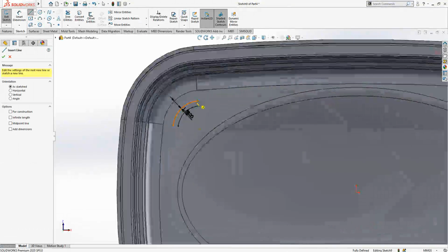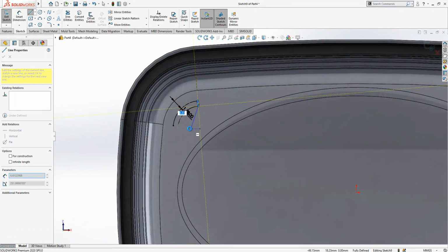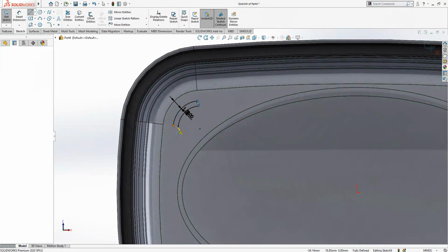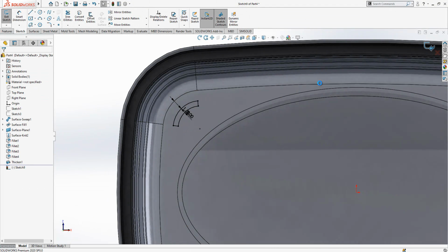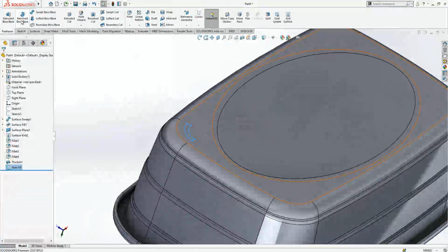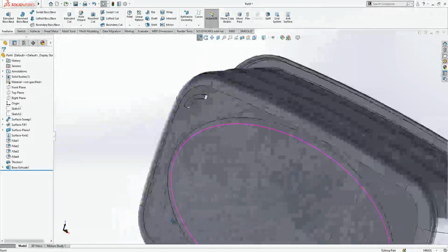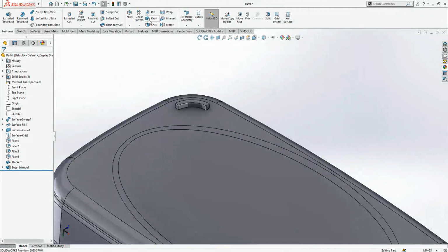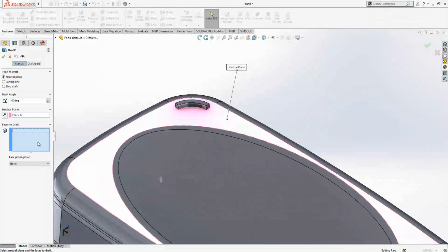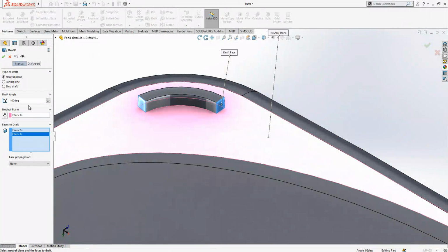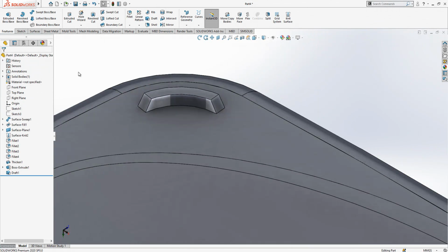And then I will combine these points with a line. And then I will make an extrude 1.5 height and with some degrees, 5 or 2. Let's make it 2. And then I will create a draft. Selected only these 2 surfaces, and I will make a 30-degree draft. I'm going a little bit fast, I realize.